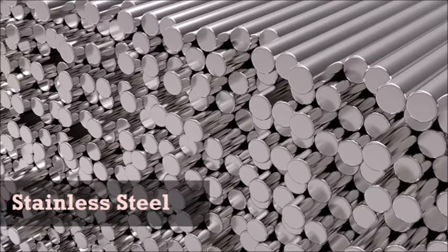Stainless steel is an alloy of iron with a minimum of 10.5% chromium. Chromium produces a thin layer of oxide on the surface of the steel, known as a passive layer. This prevents any further corrosion of the surface. Increasing the amount of chromium gives an increased resistance to corrosion. The presence of the stable film prevents any additional corrosion by acting as a barrier that limits oxygen and water access to the underlying metal surface.